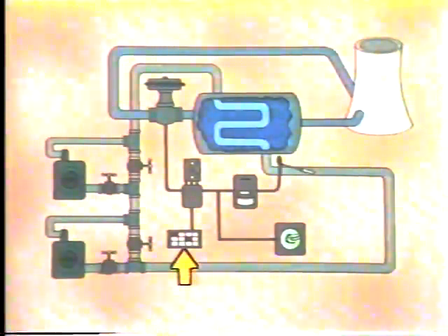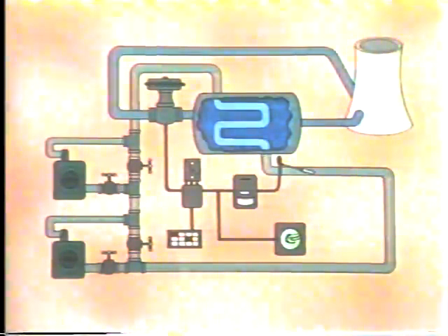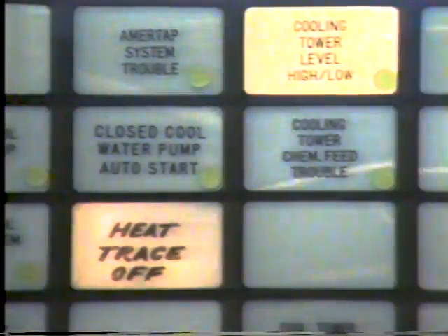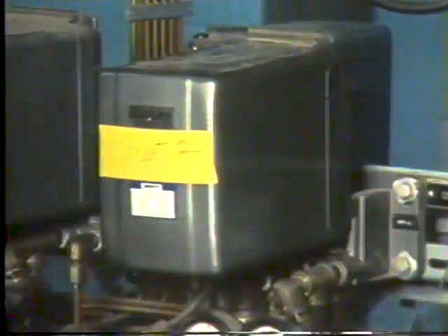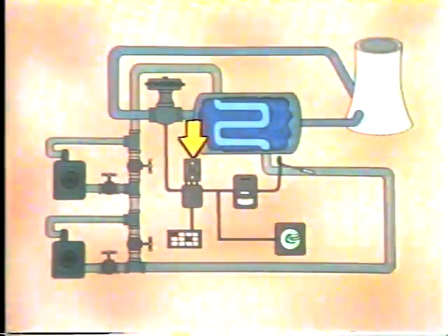There's also an alarm similar to this one in the control loop. The alarm indicates a high cooling water temperature. The system's controller is a typical pneumatic proportional plus integral, or PI controller. There's also a hand station in the control loop.